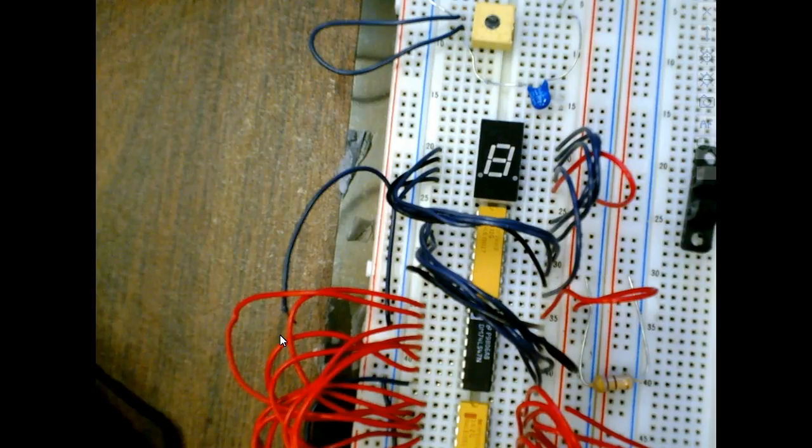In displays, we call this blanking. No, this is RBI. RBO doesn't do anything. It's an output. I don't know why they want us to do that. So scratch out RBO and put RBI, which is switch 2 on B. We're closing switch 2, so let's make that correction there.